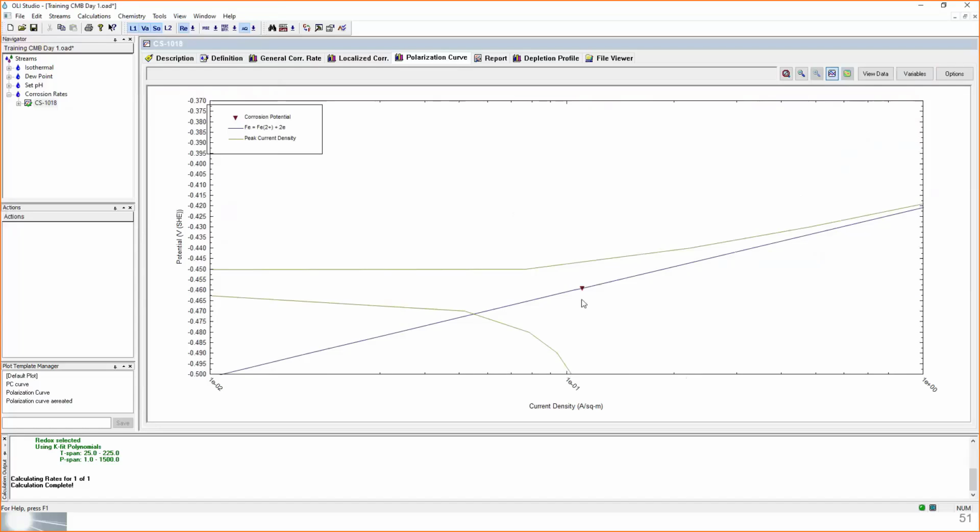I need to find out exactly if this peak current density will give you that repassivation potential. I know that we calculated based on this peak current density theory, but I don't see how it can be interpreted from the polarization curve. I will be back with that answer next class for you. Thank you for that question. That's a very good question.